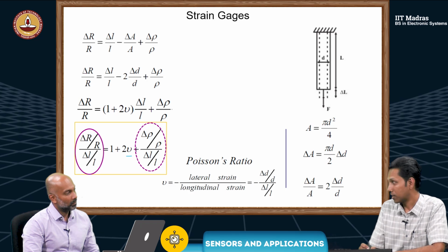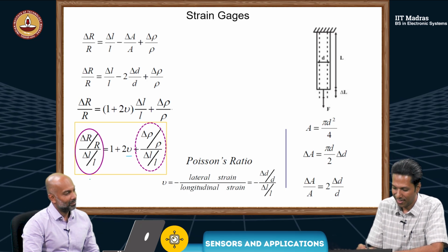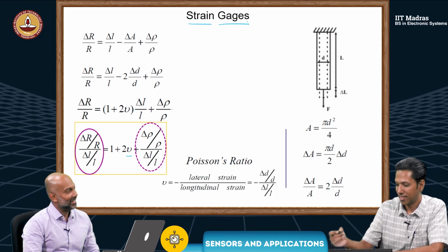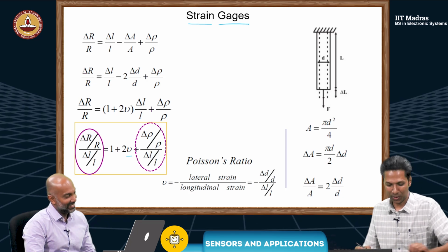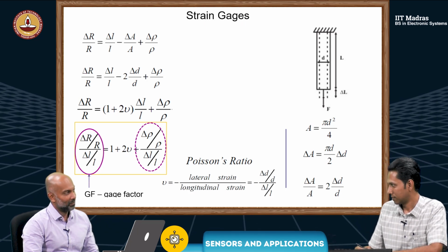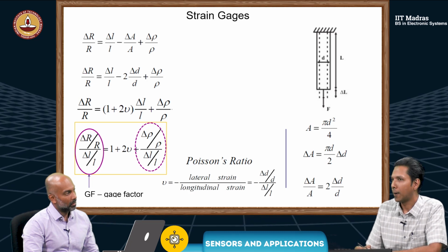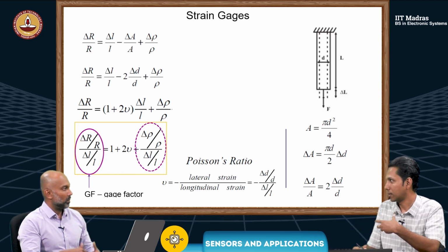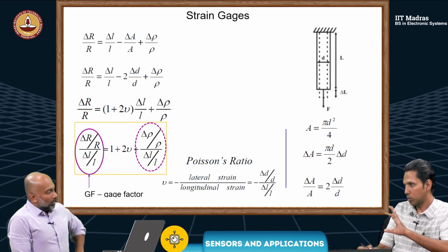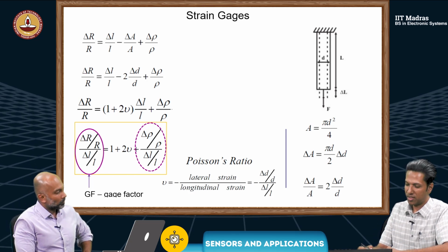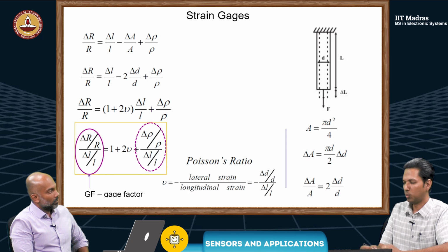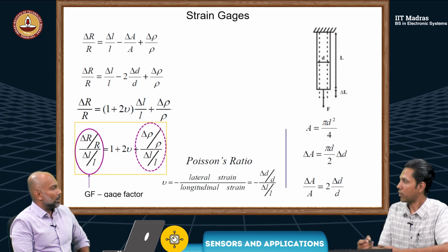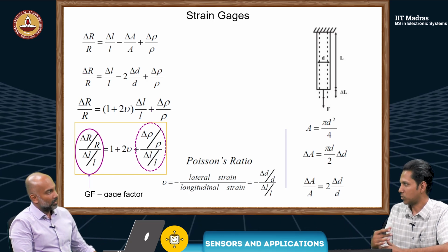Okay. So that factor you may want to call it as something. I think, since it's a strain gauge, I would say it's called gauge factor. Yeah. So that's called gauge factor. So I've seen for metallic strain gauges, the conductive ones we have mentioned in the previous slide, it's normal conductors. Yes. So if you use metallic strain gauges, the gauge factor is maximum 2. Yeah. 2 or less. That's what we have seen.